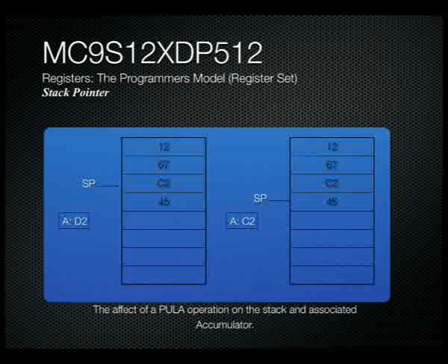So you can see in this case, the pull operation effectively moves the value where the stack pointer refers to into accumulator A, and then increments the stack pointer by 1. So it's a post-increment operation.